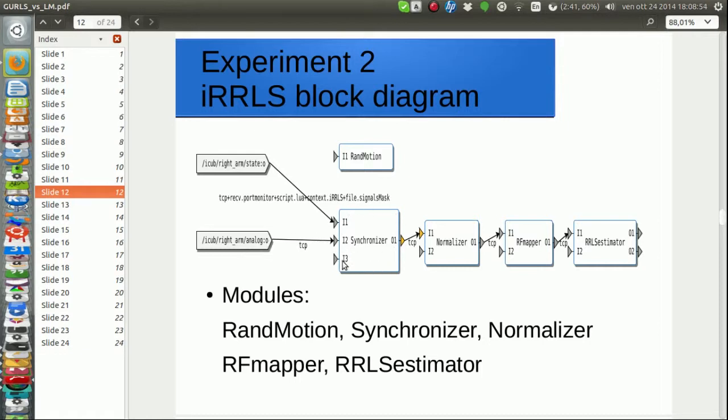They input into a synchronizer module in which the velocity and the acceleration at the joints are estimated using the velocity observer module. The velocity observer libraries are available on Robotology in the iCub-main repository.